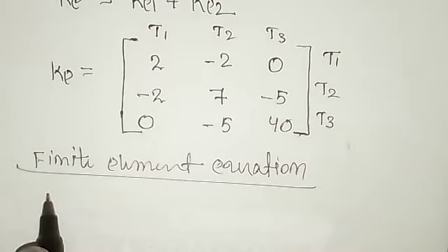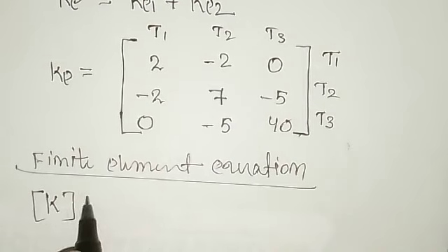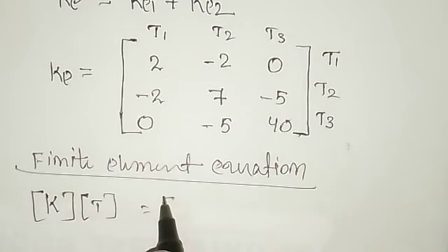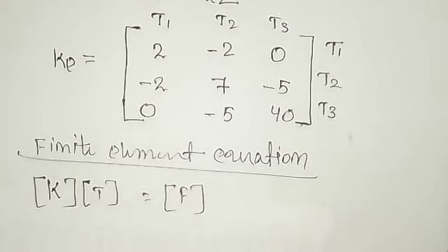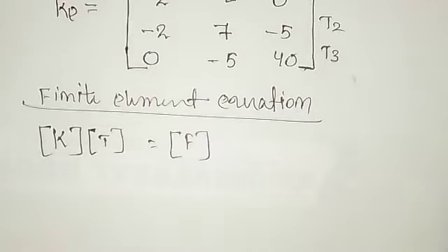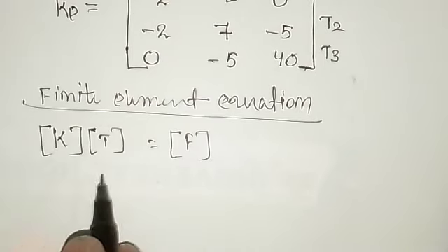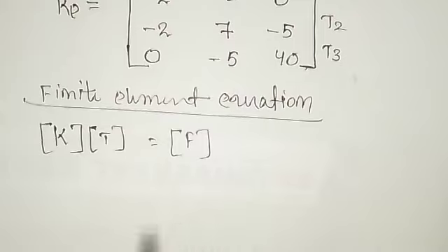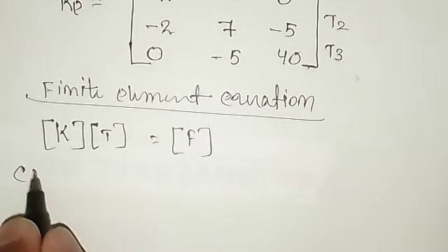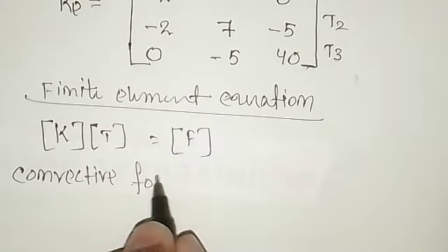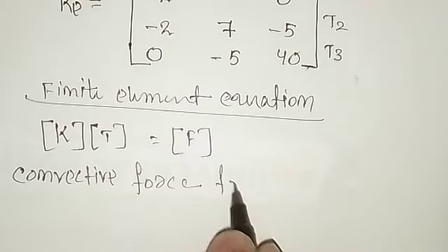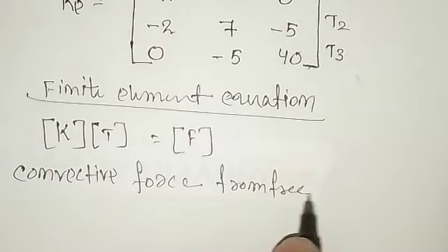This is the thermal problem, so the finite element equation will be KT is equal to F. K is the stiffness matrix, T is the nodal temperature, and F is the load vector, which is basically the convective load vector. First of all we have to find out the convective force from the free end.